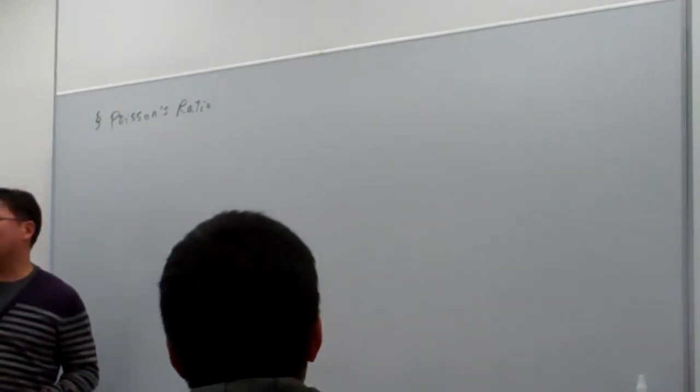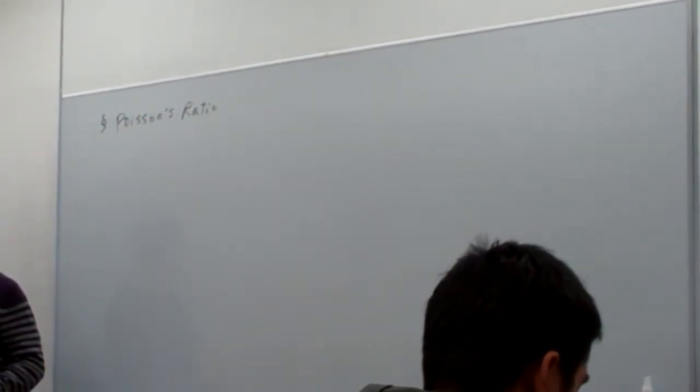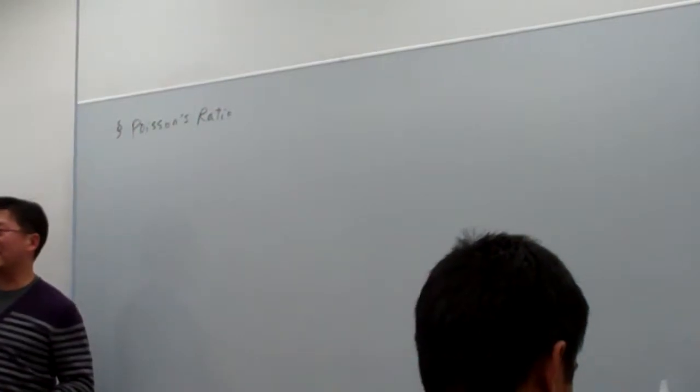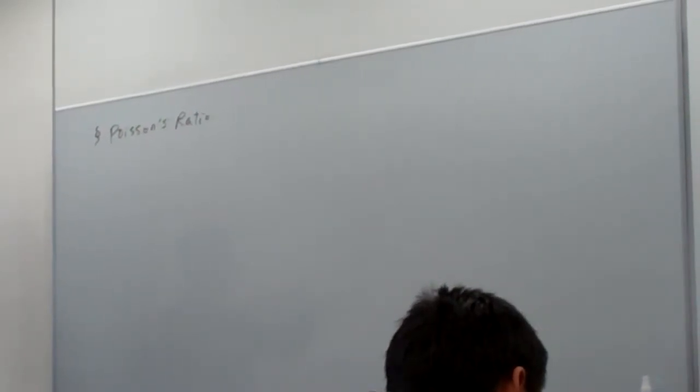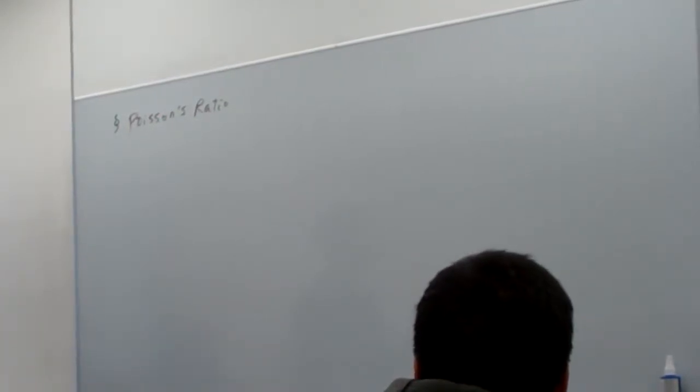Poisson ratio is this. So far, I have given you an impression which is not so accurate, not so precise. So far, I gave you the impression that all the material models we've been working on are one-dimensional. If you imagine all the examples as one-dimensional, that means if I apply a load in the horizontal direction, we only calculate the horizontal deformation or strength. We haven't considered the corresponding vertical deformation or vertical strength. But in real cases, all materials are three-dimensional.